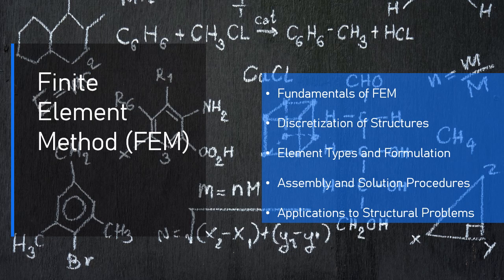4.2. Stress analysis of plates and shells. 1. Plate structures. FEM is ideal for analyzing thin, flat structures like plates, where bending and in-plane forces are significant. Plates may experience various load types, including uniform pressure, point loads, or bending moments. Application example: analyzing the deflection and stress distribution in a large concrete slab subjected to uniform loading, e.g., a floor slab or a foundation plate.